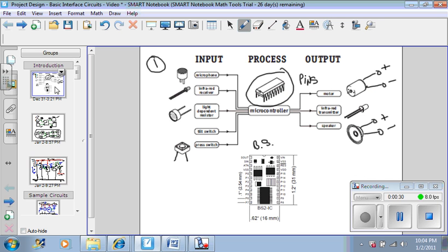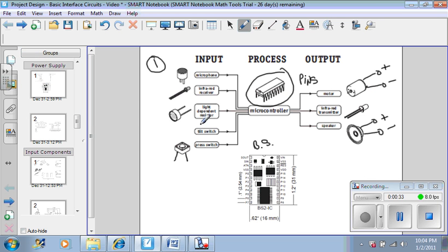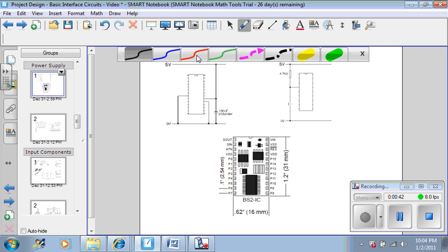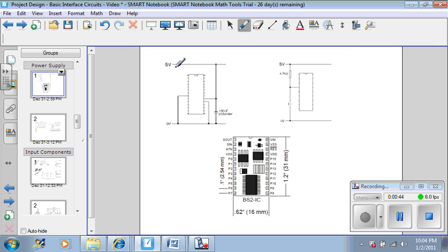From the beginning, as I mentioned before, you have to set up some type of power supply. Usually that corresponds to the top and the bottom. And sometimes your microcontroller might need a reset switch to restart the program. So here's an example of how you would connect a reset switch to the microcontroller. And over here is how you might connect the power, VSS, VDD, and VSS.